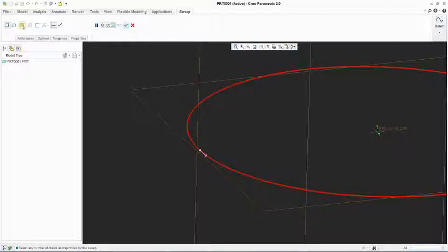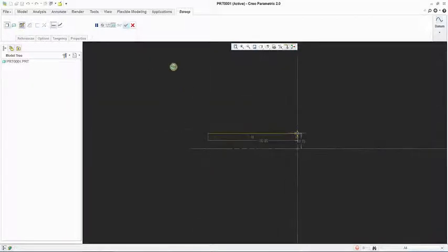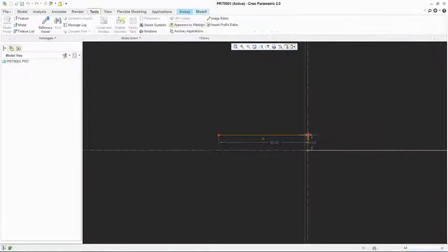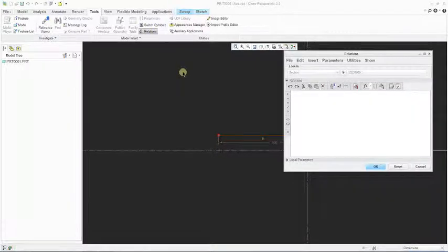Okay, let's be in the sketcher and change the relation. How do we do that? Go to tools and say parameter relations. Now in this place, I'm going to use the same equation, right? So I had the trajpar into 360 into 10 or 20 or whatever number of turns that you wanted. The same thing I'm going to apply in this place also.